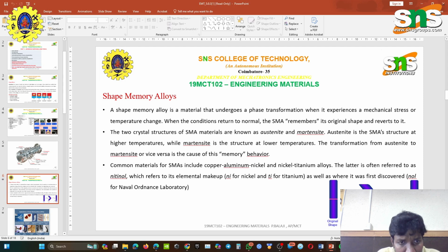The two crystal structures of SMA materials are known as austenite and martensite, which are available in our iron carbon diagram, as you can see in my last videos. Austenite is the high temperature structure of the SMA, while martensite is the structure at lower temperatures.